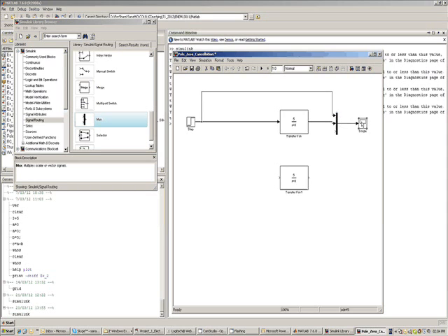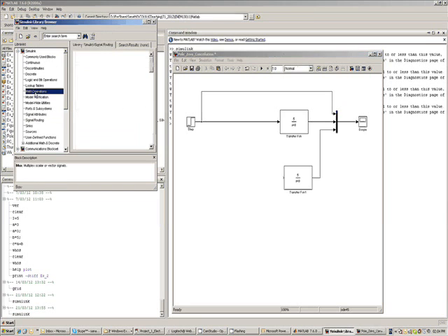So what I do is I increase the input ports of the multiplexer block, right? Keep it like this, connect the output of the closed loop system. We still haven't constructed the closed loop system. Let me do it little by little.